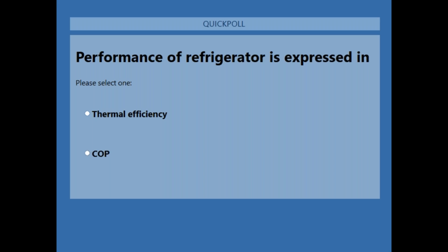We also looked into constructional aspects of heat engine and refrigerator. We said that a heat engine essentially would have a prime mover like a turbine, for example, or an engine proper, which would convert the heat to work. Whereas in your refrigeration system you would have essentially heat exchangers like evaporator and condenser, and some devices for changing the pressure like compressor and expansion devices.